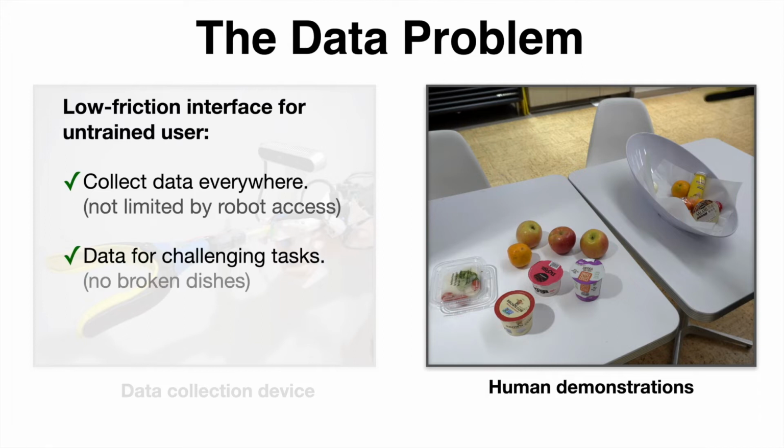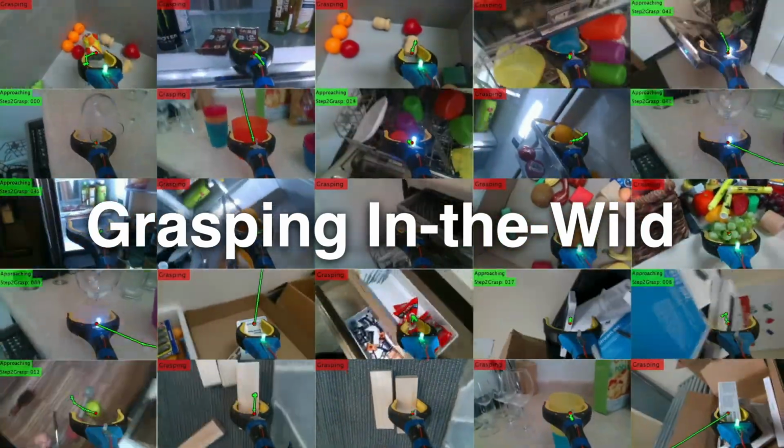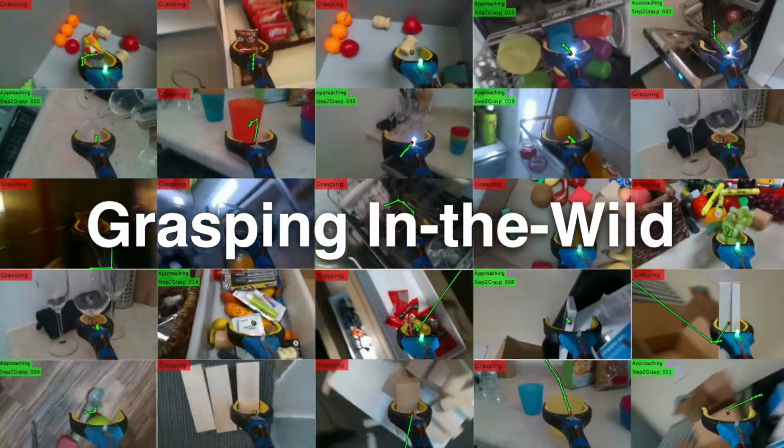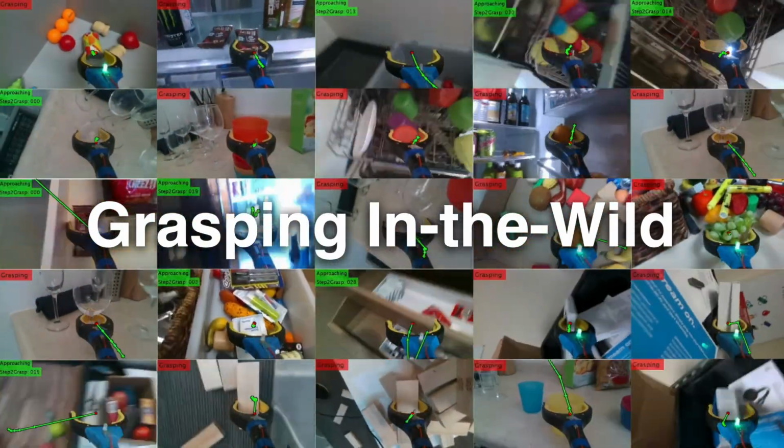And because it is a human controlling the gripper, we are able to collect data for very challenging tasks such as loading dishes in a dishwasher, without worrying about robot failures that may lead to broken dishes, for example. And finally, since the gripper tool is designed to mimic the real-world robot end effector and sensor, the data collected here is much easier to transfer to real robots. In total, we collected more than 7,000 trajectories, and we can compute the full 6-DoF pose trajectory of the end effector by using 3D reconstruction.